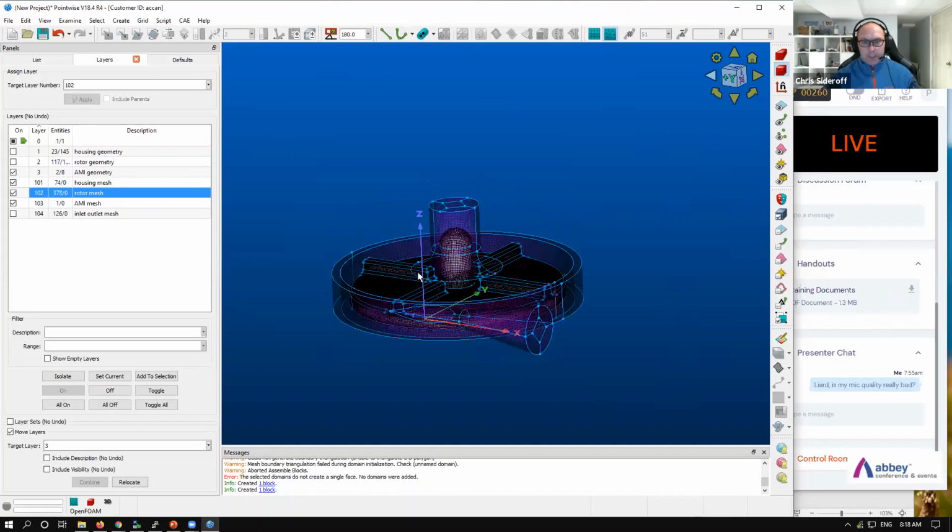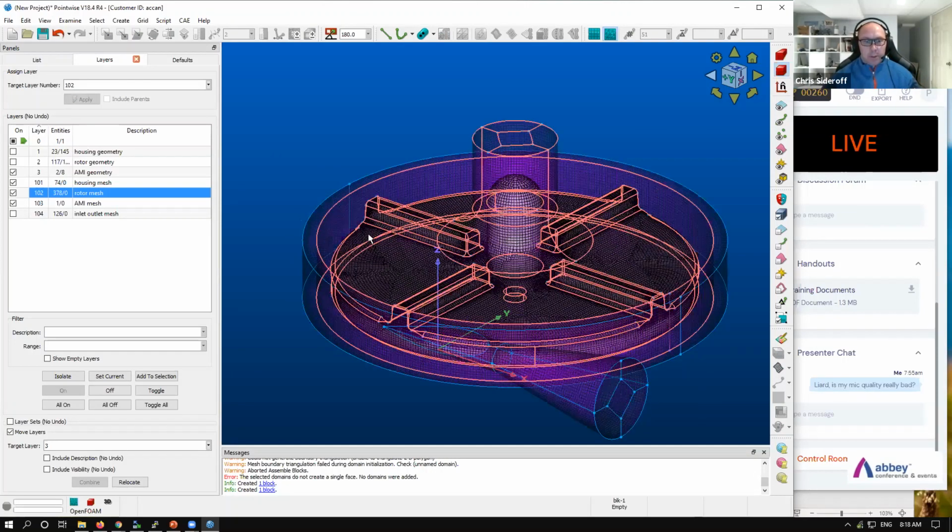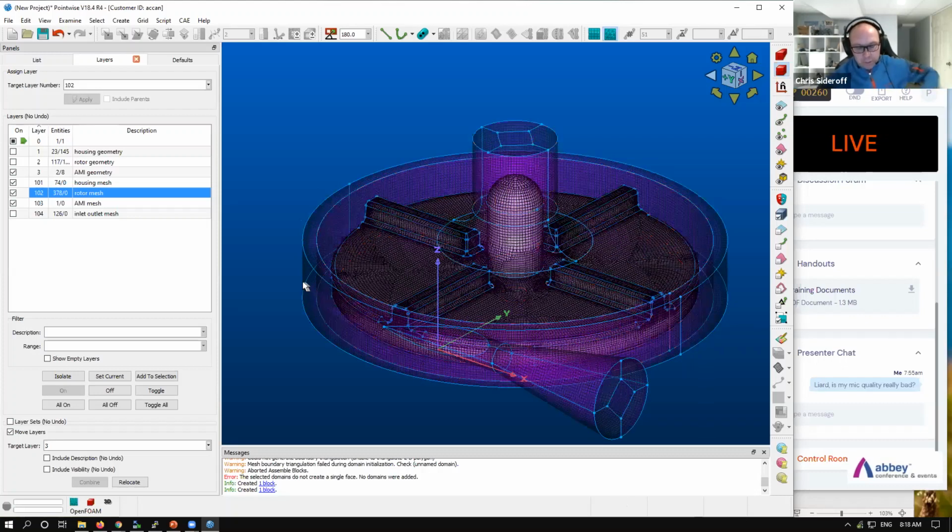All right, so the last step here now is we need to populate. Again, this is something unique to Pointwise. We created this block, which is going to serve as the volume mesh. Now we have to populate it with the actual volume cells. So it's a two-step process for unstructured volume meshes. And we're going to do that using Pointwise's T-Rex method, which is its anisotropic tet mesher.